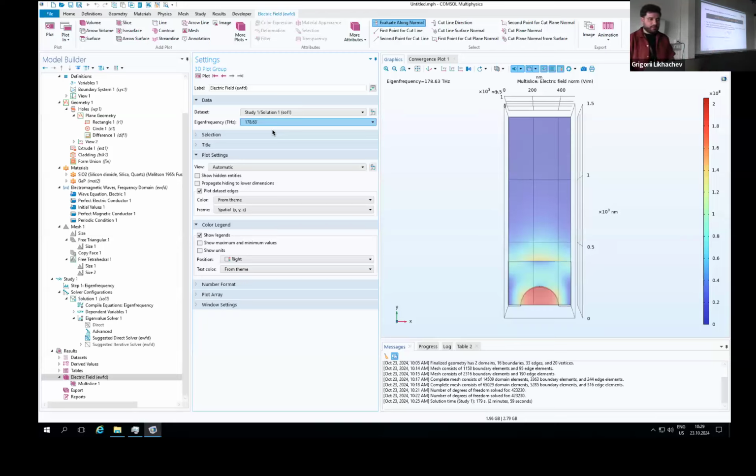From the group delay of the PCR, if you want to do the whole cavity, you take your beautiful simulation of the waveguide in 2D from COMSOL. You can get beta 1. You multiply by the length, so you know how long your waveguide is, and you get the overall group delay of the whole thing.